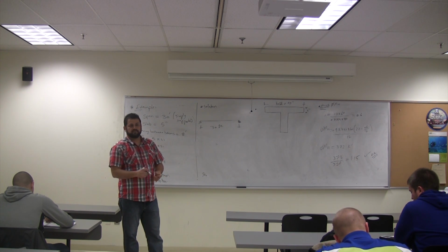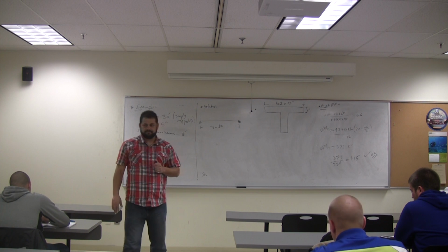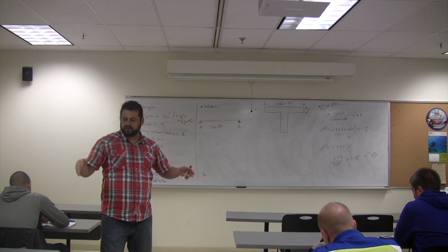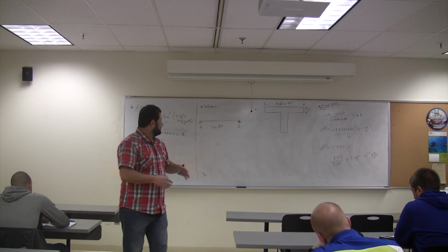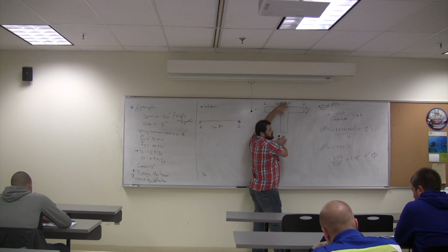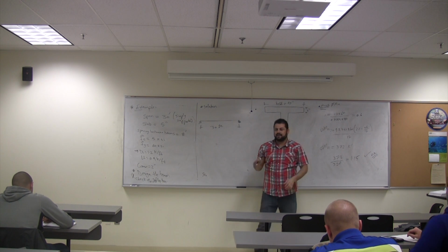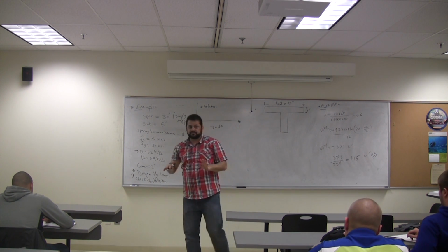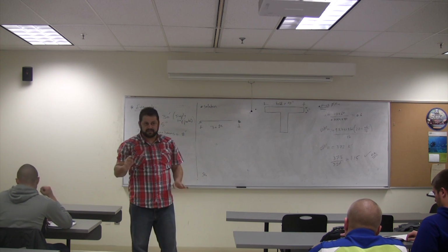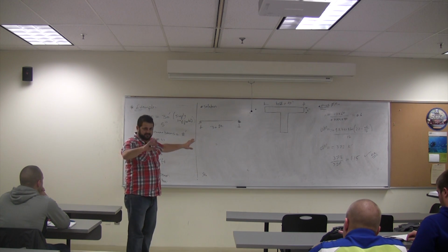To know the slab section thickness? The first thing we design is the slab. That's the first thing we design in reinforced concrete, because we know the support of the slab is the beam. So the thickness we have, the thickness of the slab is determined such that the deflection doesn't have to be checked. Now, good? That answers?